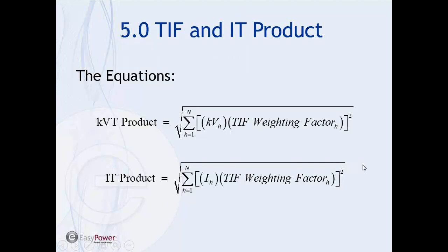Similar to an RMS calculation. So this gives you a total figure that lets you discern what type of interference level you have, similar to total harmonic distortion, but it's weighted. It's weighted according to voice, to spacing, to harmonic, to frequency response of the equipment, etc.